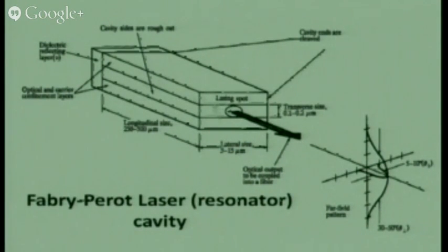So this is a Fabry-Pérot resonator, where this acts as one mirror, this acts as another mirror, and then you have this cavity which has this height, this width, this length, and based on this we have the different modes coming out of it. And this is the Lambertian or Gaussian output of the light which is coming out from this spot, right? It can be in this direction or in this direction. If you see the laser beam output, it is spreading in this direction and in this direction, but it is coherent, so it takes a longer path for the dispersion to take place.